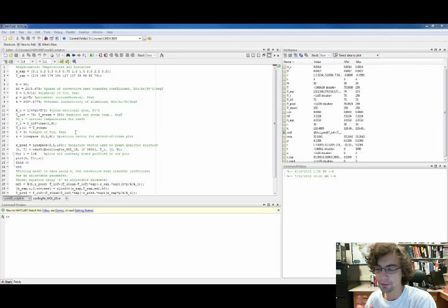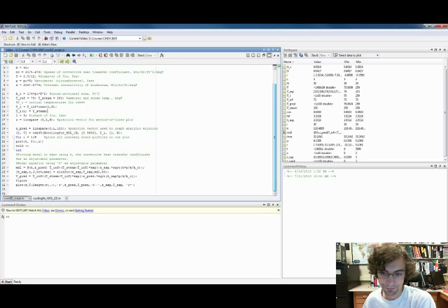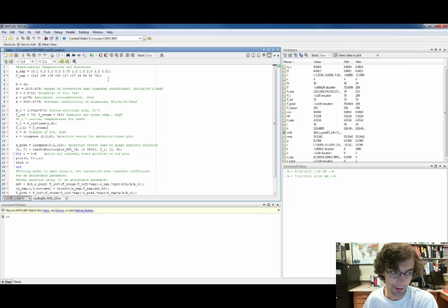Now to think about the nlinfit. Ode45, of course, was numerically solving a differential equation. Nlinfit, on the other hand, is basically a regression type function. The neat thing about nlinfit is that if you know the form of the equation that you want, you can specify that and then use adjustable parameters to determine the best fit.